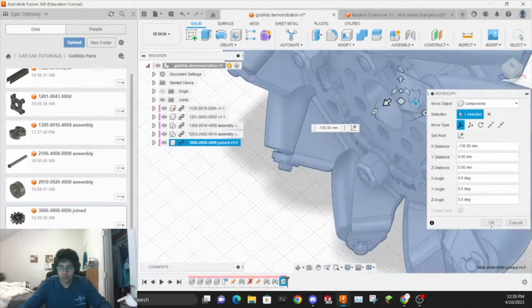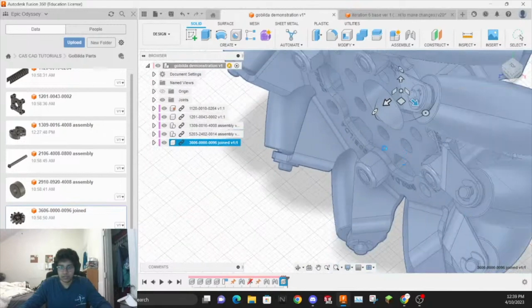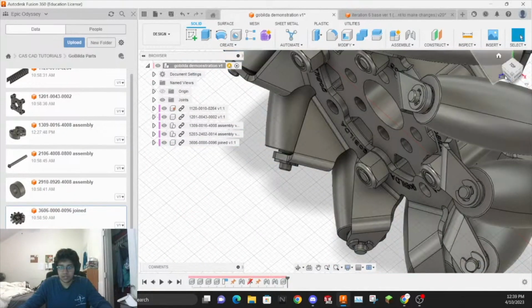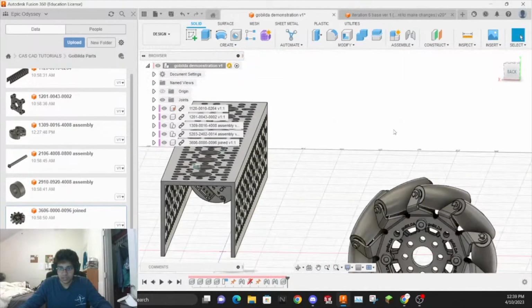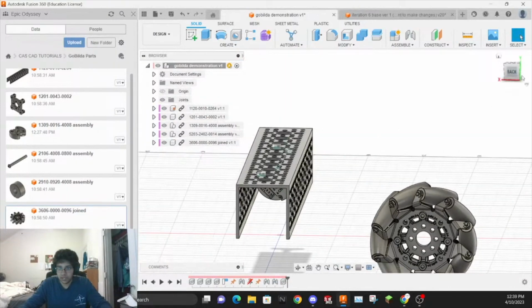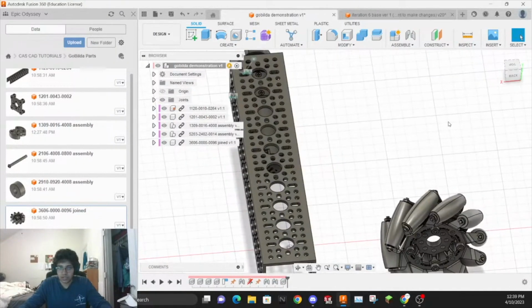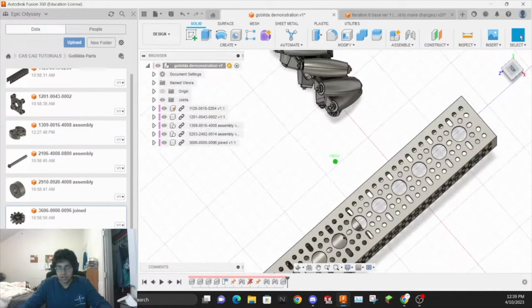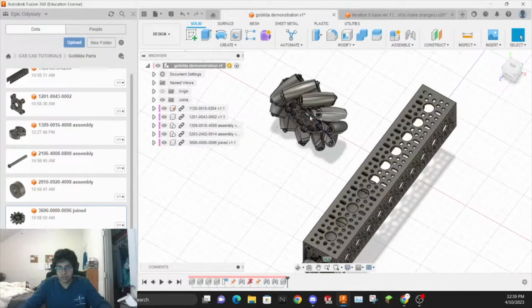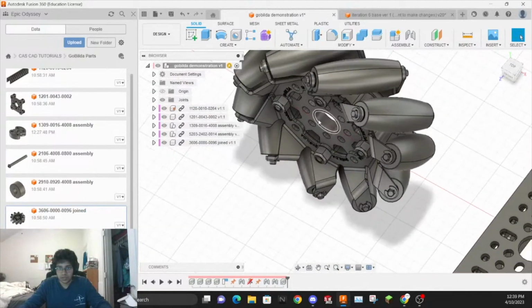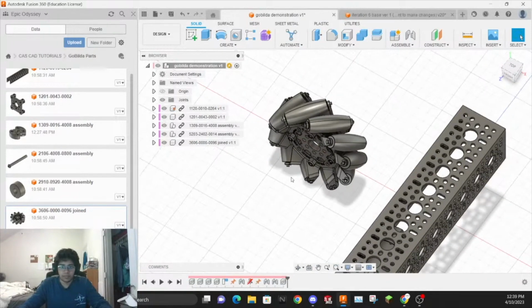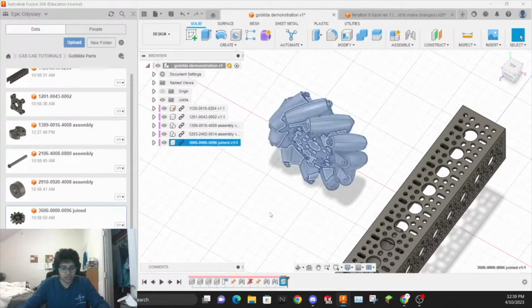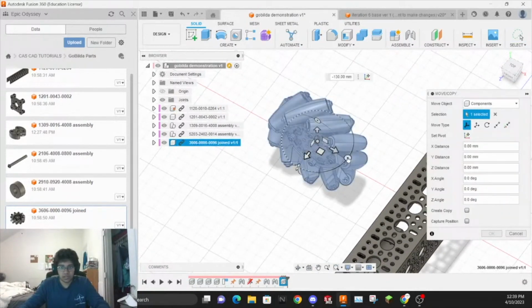You have one side of the wheel that's very close to the outside and one side that's recessed. This recessed part here, you see that? You want to avoid attaching the sonic hub onto the recessed part, and instead you want to attach the sonic hub to the part that is not recessed. That will keep your wheel from hitting a bunch of screws and just not working in the real world.